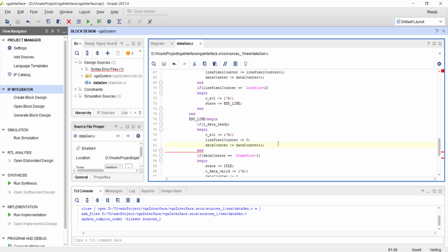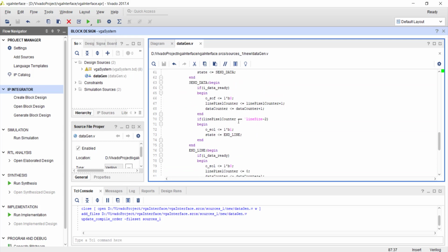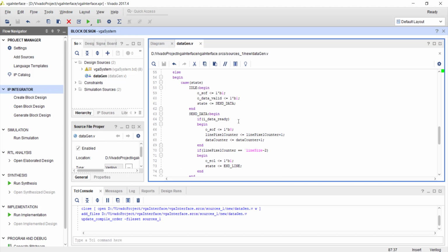So my plan is to create some vertical color bars on the screen. You might have seen that is the standard video testing pattern. Now I'm not planning to have like 7 or 8 vertical lines which you usually see. We just want to test the minimum functionality. So I'm planning to have 3 vertical lines. Let's say 1 red, 1 green, and 1 blue. Okay, so 1/3 of my screen should be red, 1/3 green, and 1/3 blue.